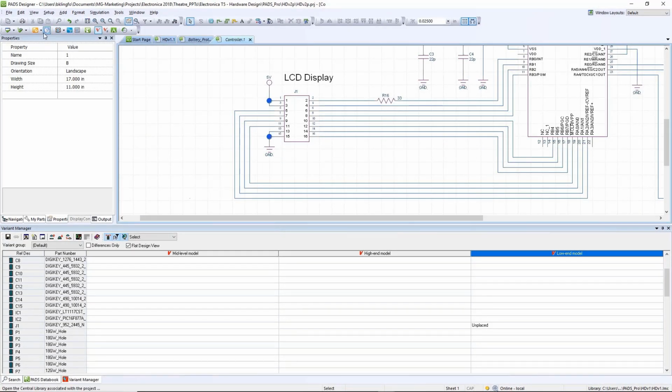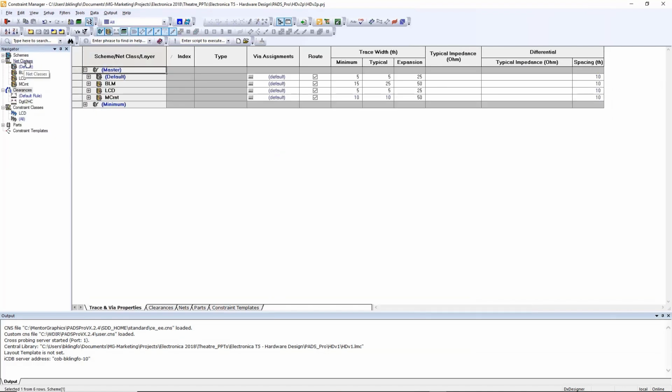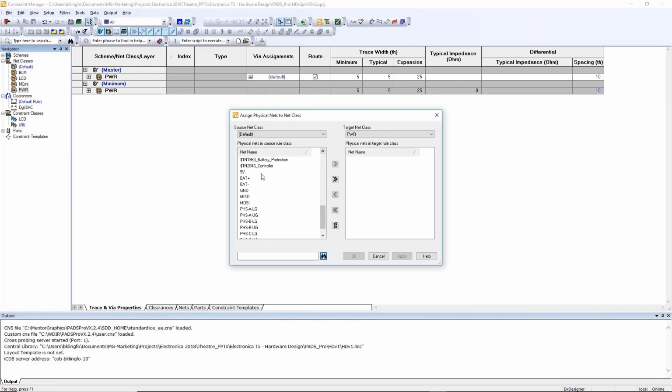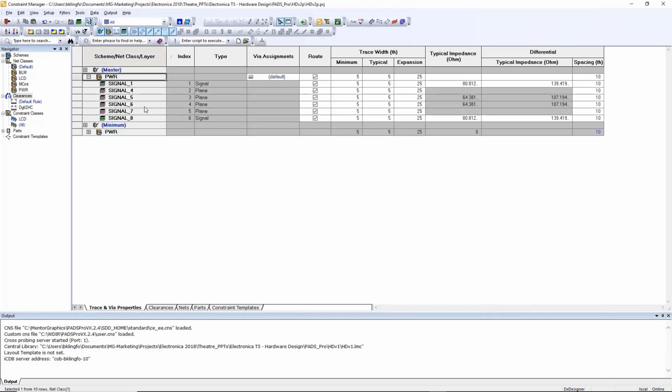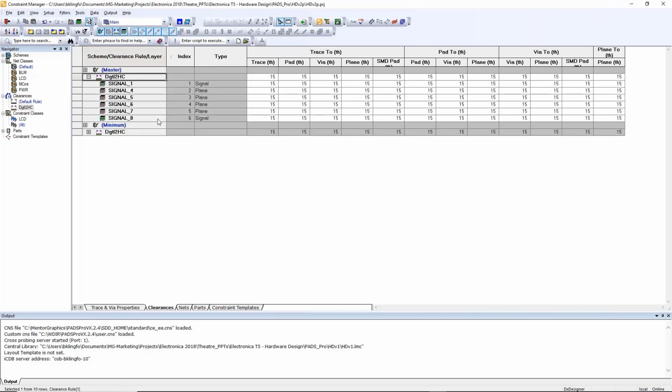Moving on, design rules are mandatory for doing a PCB layout. In many cases, it's much easier if you can enter as many design rules at the schematic level when you're thinking about your electronic circuits, or you've done simulation. So from Designer, we can open up the constraint management system, which is the same rule entry system you would use in the PCB layout.